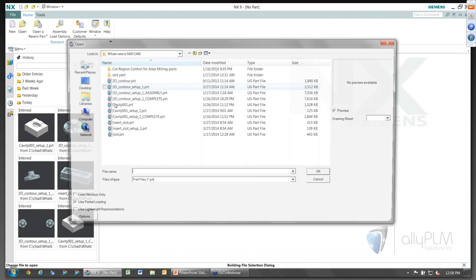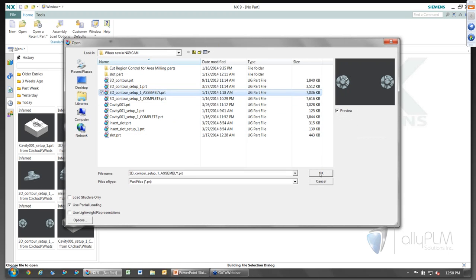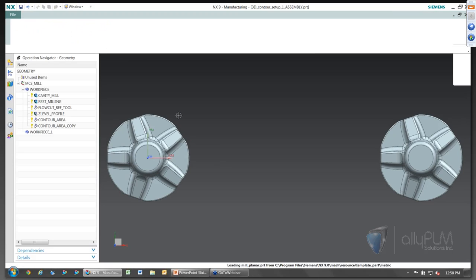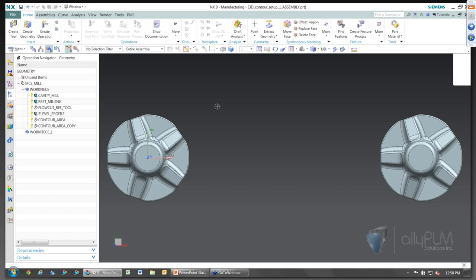All right, the last thing that I want to look at today is if you have an assembly, maybe you have multiple parts in an assembly, and if these parts are identical, we have the option available now to paste with reference. Before, we used to have to just paste an operation, and then it was really not associative. We also had the option to maybe instance or copy multiple operations, but again, that was not associative.